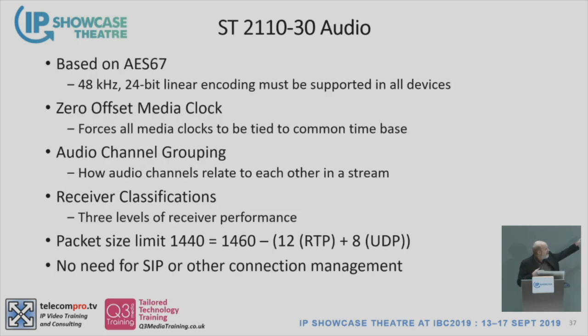So based on AES67, 0 offset media clock, audio channel grouping we'll talk about in just a minute. There's different receiver classifications that we added in 2110. And the packet size limit adheres to the limit we talked about before with ST2110-10, 1460. We take away our RTP and UDP headers, so our payload for audio is 1,440 bytes or octets, depending on how you want to say it.